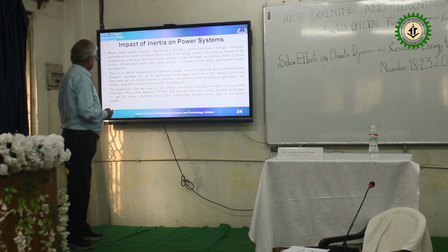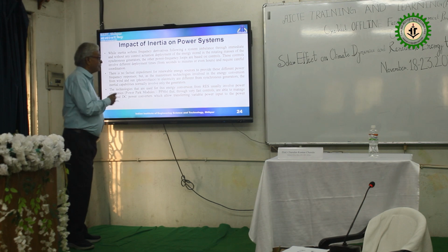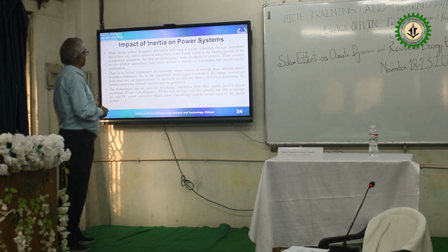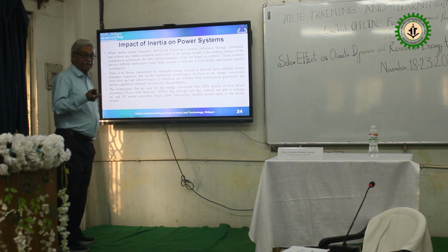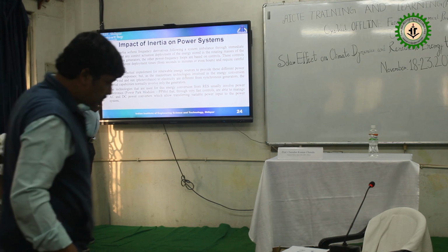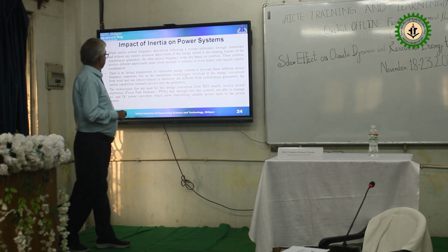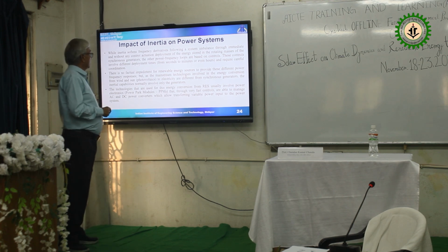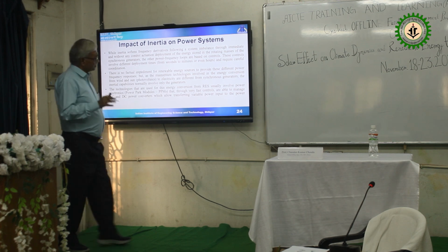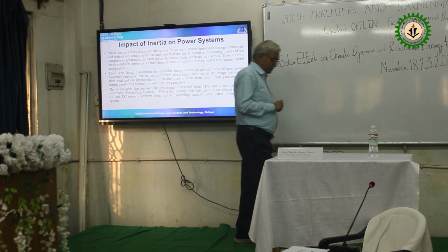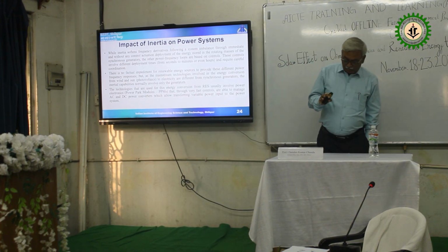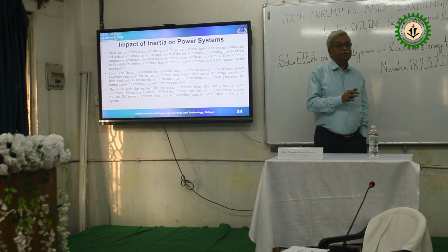So the impact of inertia, I have already talked a lot about. When inertia softens frequency, it can reduce the deviation, if there is additional inertia from the turbine. If there is no inertia in the turbine, it cannot soften the frequency following a system imbalance, through immediate deployment, without any control actuation, of the energy stored in the rotating axis. So what is called synthetic inertia? Say there is a 2 megawatt power demand suddenly, and we cannot change the turbine and all that.